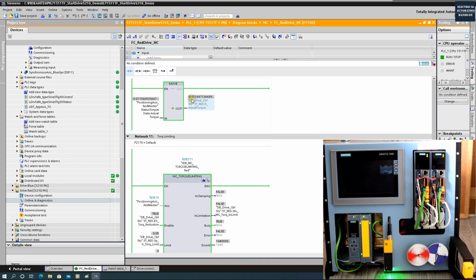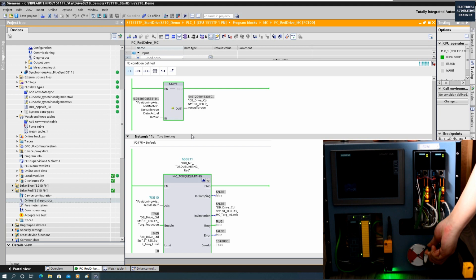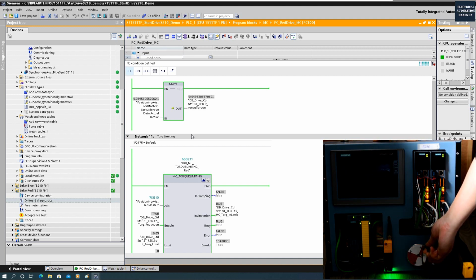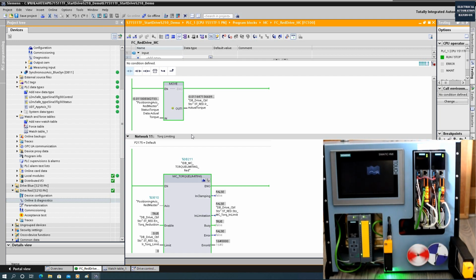Okay, now it's running backwards. That's why this shows a negative value. And let's see if this negative value also works. All right. Apply the load. Okay, the motor stopped, and we can see the actual torque is negative 0.05. Release. Apply. Hold a couple of seconds, and release. So we will see the motor just keeps running continuously without any fault issue, and the negative value also works.